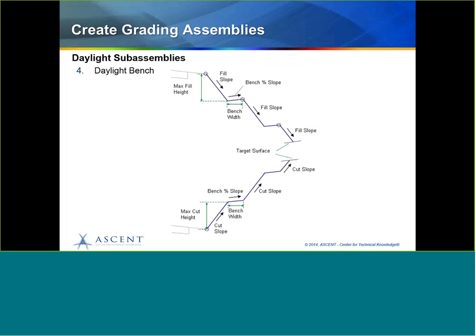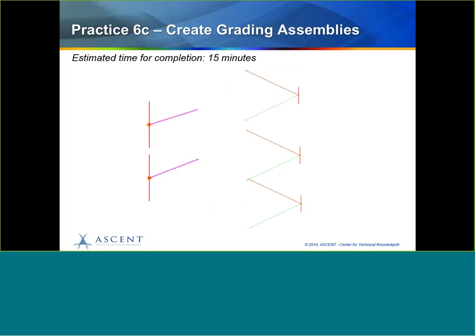The last one I'll mention is a daylight bench subassembly, and this creates repeating benches as needed at specified heights and widths, as well as slopes, until it finds a daylight to surface to. The cut benches can have different parameters than the fill benches if that's required.